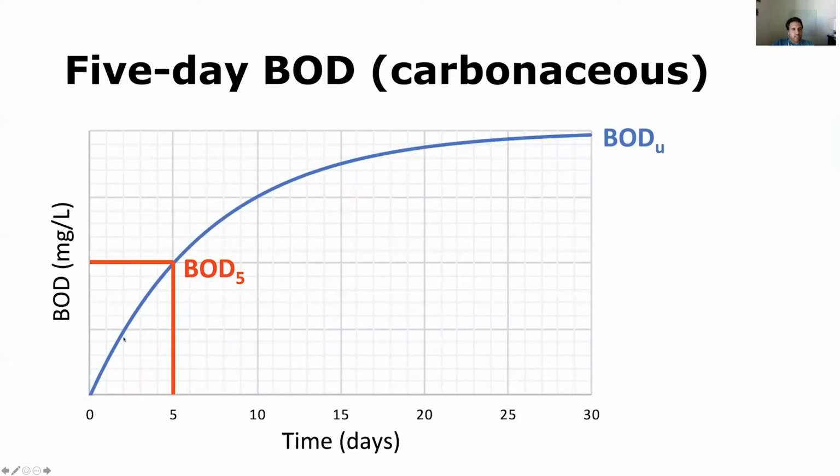All right, so the BOD will continue to increase until it finally plateaus, but this happens over a much longer period of time. We conduct the test at a standard time of 5 days. So it's important to note that if you're talking about the total amount of organic material expressed in terms of BOD, that number should actually be higher than the BOD concentration that's measured in the lab, which is BOD over a period of 5 days. The units of BOD, however, are milligrams per liter, just like the units for COD, and we can use this as a surrogate measurement for, again, the concentration of organic matter in the wastewater.